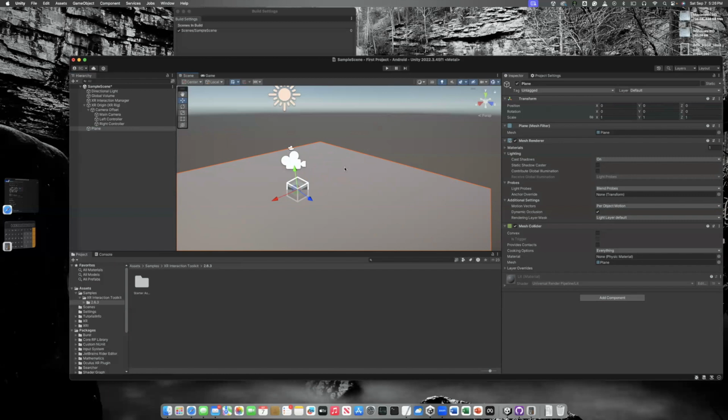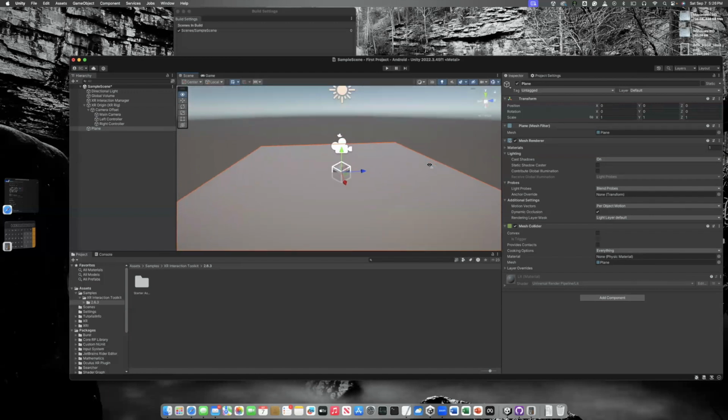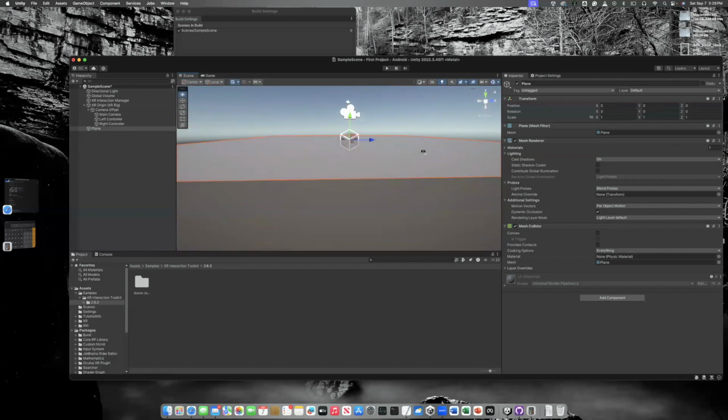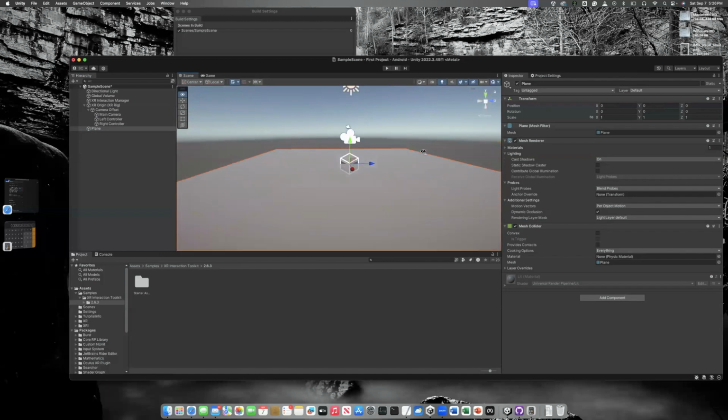So I right click, and then the mouse pointer changes to this eye looking thing, and then using WASD I can move in the scene window. To move down, you press the Q key, and to move up, you press the E key.